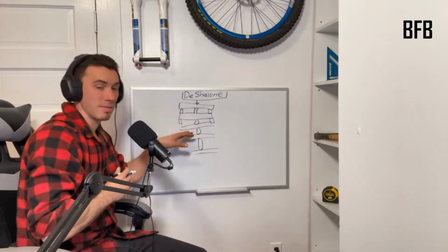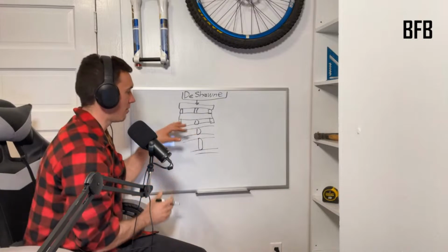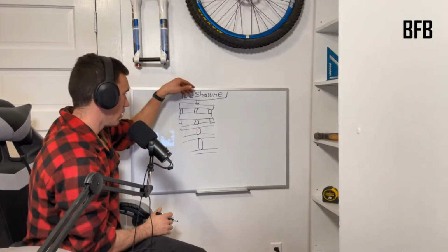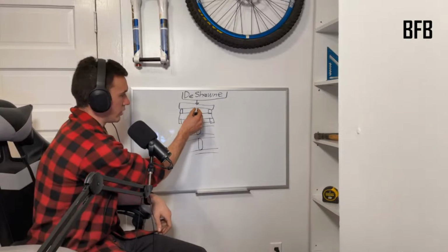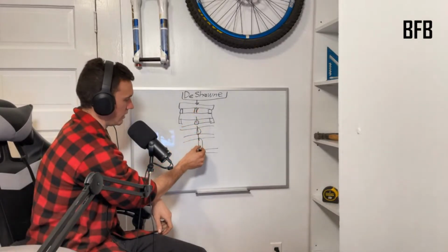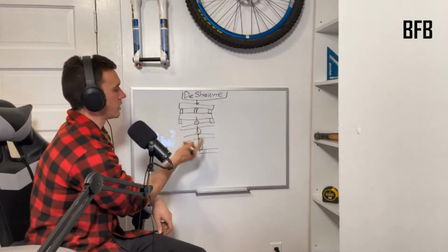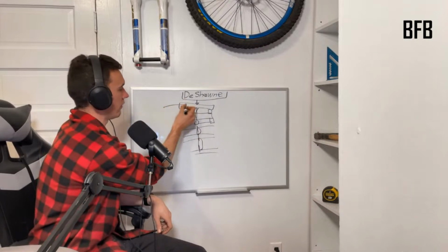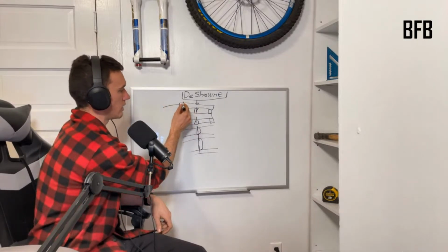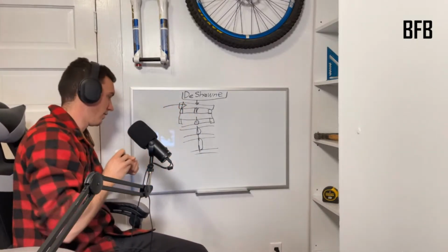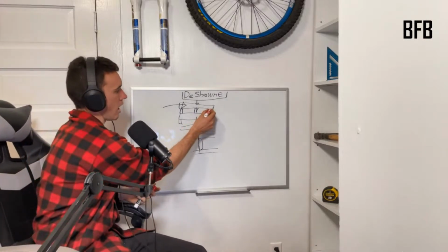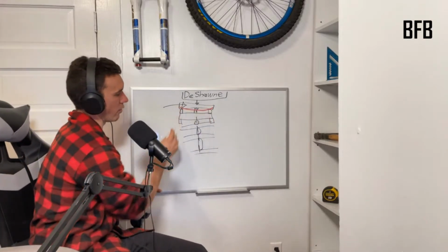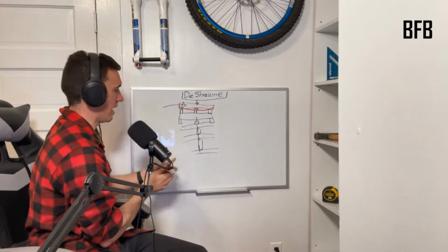If we were to put blocks between all of these, then what would happen is the load that's coming through this first one is going to be transferred down and down and down and down and down. And each one of these beams is going to contribute to the first one, not, I'm going to grab a different color here. I have colors for a reason. It's going to make the first one not deflect downward. They're all going to help it out.